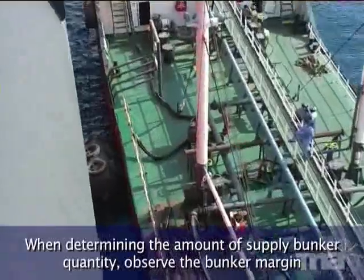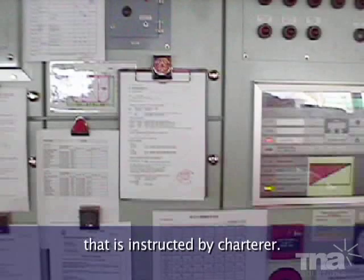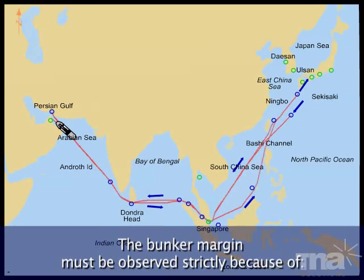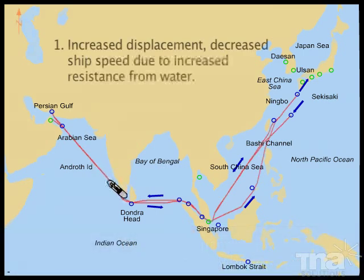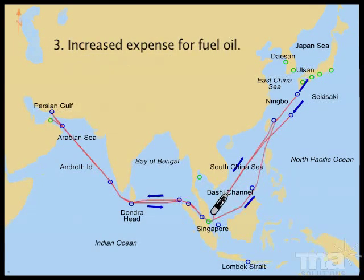When determining the amount of supply bunker quantity, observe the bunker margin that is instructed by charterer. The bunker margin must be observed strictly because of, one, increased displacement, decreased ship speed due to increased resistance from water. Two, decreased loadable amount of cargo. Three, increased expense for fuel oil.